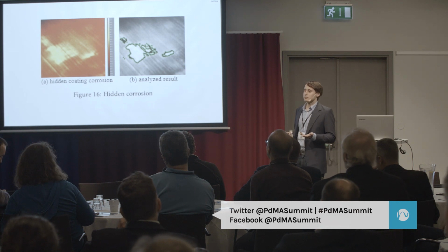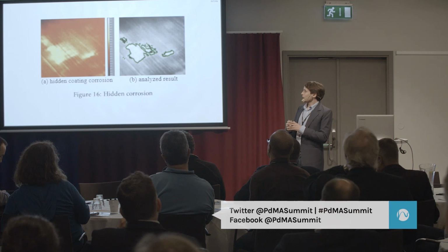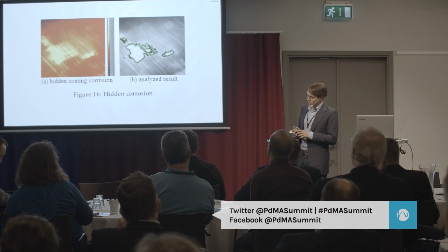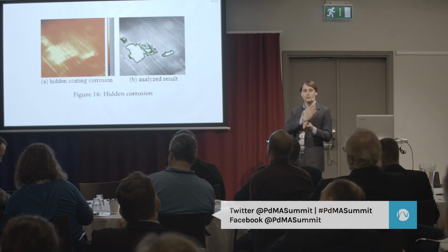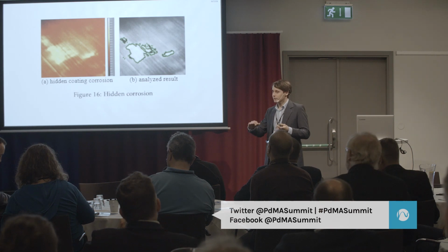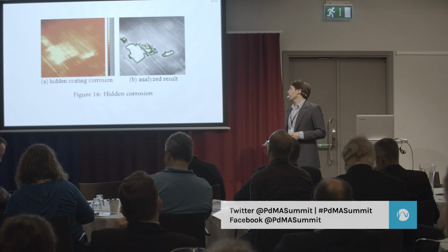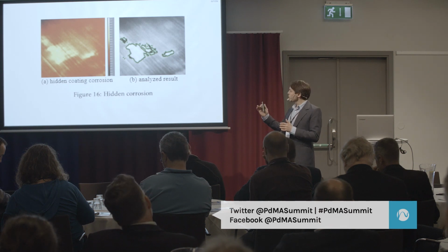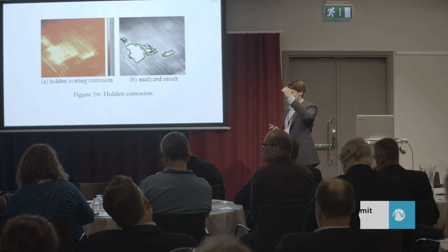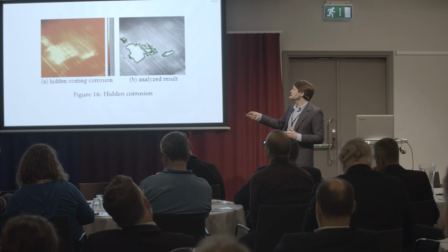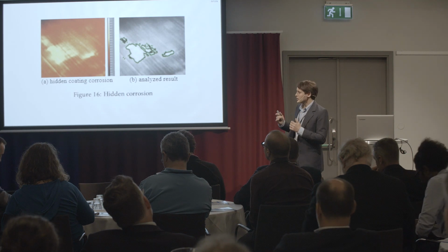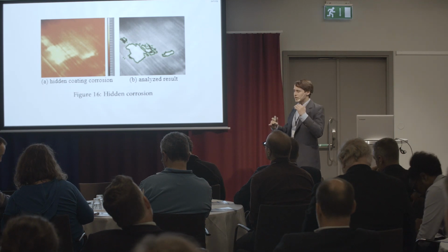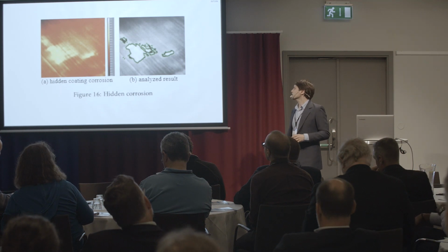What it does is it can reveal corrosion that is behind or under the surface, right? So the idea with the thermal camera is that, in the area where the metal is clean, if you apply a heat source, the temperature goes up much faster than in a corroded area. So they emit different levels of radiation, and you can measure that with the thermal camera.